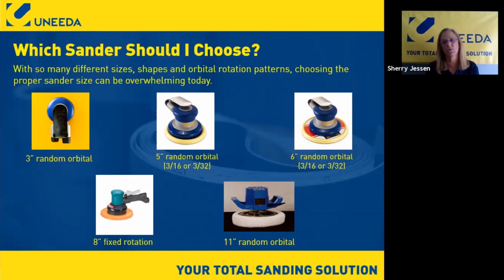The 3-inch orbital, I actually really like this little sander. I've sold a lot of them in solid surface. And it is the perfect sander for the bowls. With a 5-inch and a 6-inch, when you hit the side of the bowl, you're only going to hit a narrow piece on either side of the backup pad. So it's really hard to blend them. Where the 3-inch will actually sit flush all the way around.